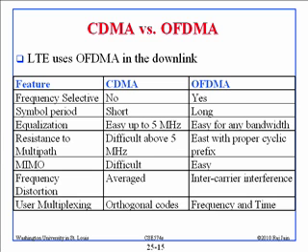Equalization works only up to 65 megahertz, and this is for any bandwidth. Now we are talking about 100 megahertz, very, very wide channels. Resistance to multipath is very difficult to do with CDMA, and it is possible to do with a proper cyclic prefix. This is what we were talking about. The cyclic prefix is that repeated part. MIMO is very difficult to do with CDMA. It's very easy with OFDMA. Frequency distortion is averaged. This causes intercarrier interference, which is what the problem actually is with respect to motion. OFDMA is not good for motion.